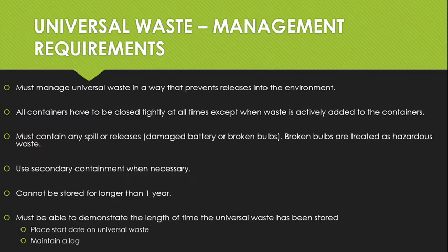Management requirements, just pretty typical stuff. They all should be closed tightly. If you have any spills or releases, you must contain it. We can't store these materials longer than a year if we've generated it ourselves. If we pick it up from a customer, it should not be on our yard for longer than 30 days. There's really no reason for it to be longer. We have 90 days to have it on site, but it should not be longer than 30 days. There's no reason for that.